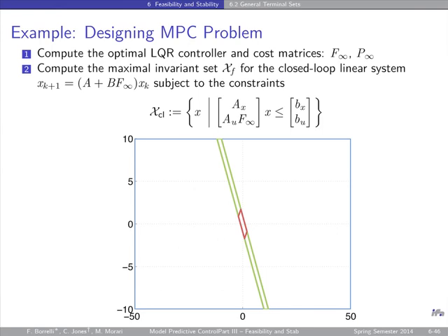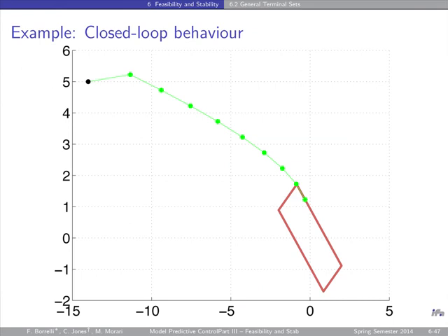You will see, I believe you used horizon 10. Okay? So you start from this set, you start from this point. You are feasible at time 0. You see that there is an input sequence that brings you in the terminal set, in the invariant set in 10 steps. Okay? You basically are done. For all the set of initial points that are feasible at step 0, you know that you will always be feasible and you converge to the origin. This was our proof before.